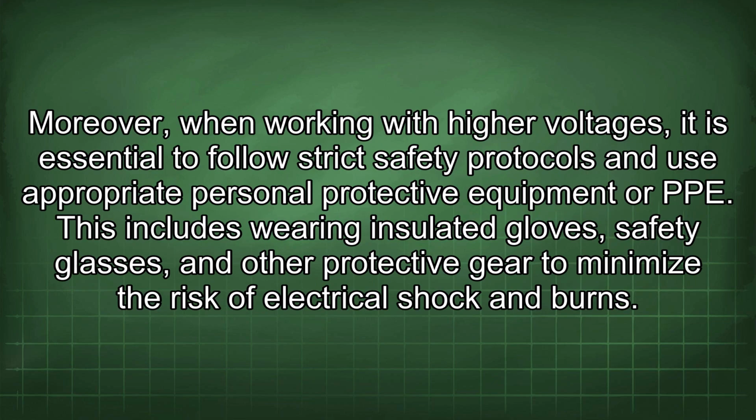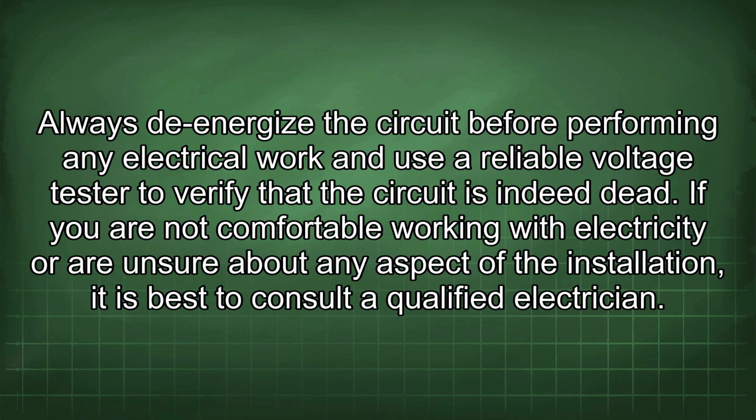Moreover, when working with higher voltages, it is essential to follow strict safety protocols and use appropriate personal protective equipment, or PPE. This includes wearing insulated gloves, safety glasses, and other protective gear to minimize the risk of electrical shock and burns. Always de-energize the circuit before performing any electrical work and use a reliable voltage tester to verify that the circuit is indeed dead.